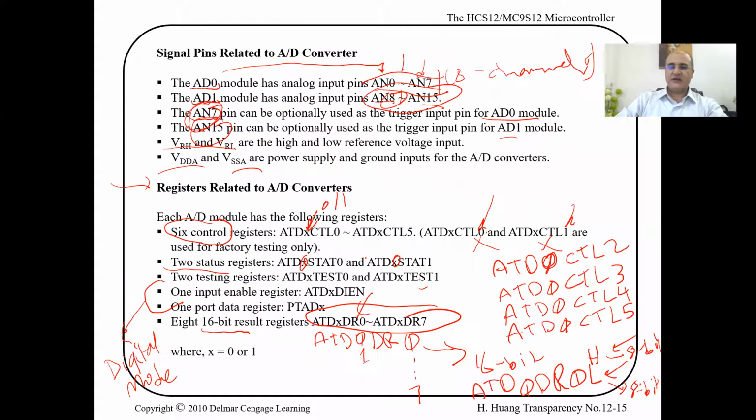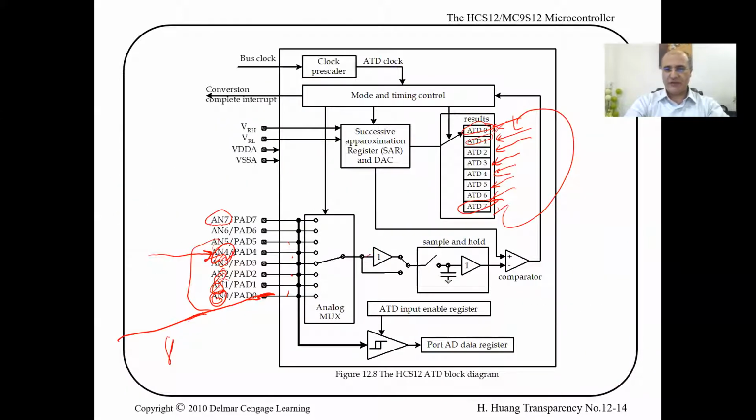Guys, this process, when you sample here, you close this switch and start charging this capacitor. This is 2 stages. Yani, there is a must to have 2 clock periods here, plus something of your choice. 2 or 4 or more time will enable the capacitor to charge more, getting to higher levels of accuracy, yani reading a more accurate voltage. Okay, but it will take more time. So it's a compromise. It is an optimization problem.